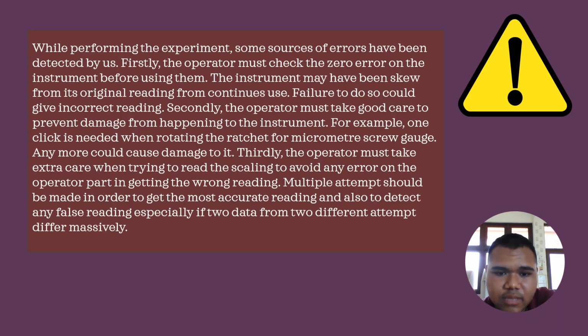While performing this experiment, some sources of error have been detected by us. Firstly, the operator must check the zero error on the instrument before using it. The instrument may have been skewed from its original reading from continuous use. Failure to do so could give incorrect readings.